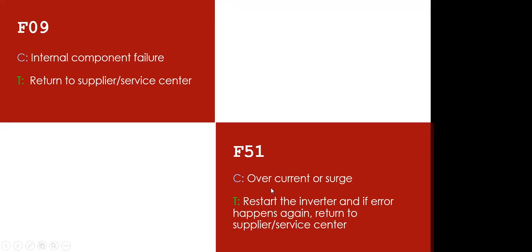So after we restart, if the inverter is okay, then we need to check the solar aspect of our work so that we can know where the issue is coming from. But if we turn on the battery breaker and the inverter starts showing the fault, it means that the inverter needs to be repaired and returned to the service center.